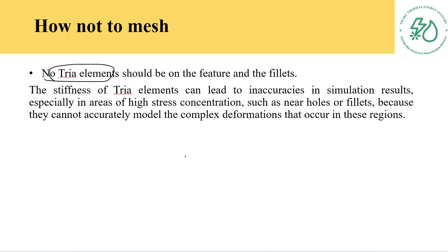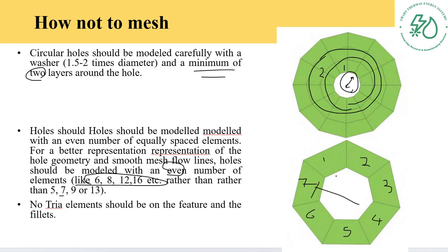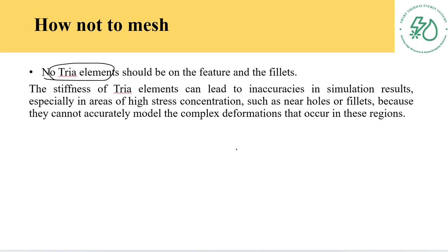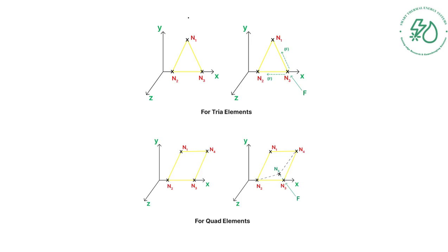The stiffness of tri-elements can lead to inaccuracies in simulation results, especially in areas of high stress concentration, such as near a hole or fillet, because they cannot accurately model the complex deformation. As you can see, you cannot use tri-elements like that around this hole. To explain it in more detail, you can see this picture.